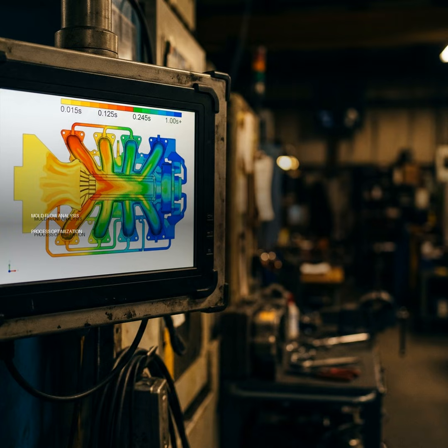And mesh thickness diagnosis, I remember you mentioned that earlier. Right? That section confirms we've balanced accuracy and computational efficiency. If elements are too thick, results are inaccurate. Too thin, it takes forever to run. We're looking for areas needing refinement, especially in complex geometries.